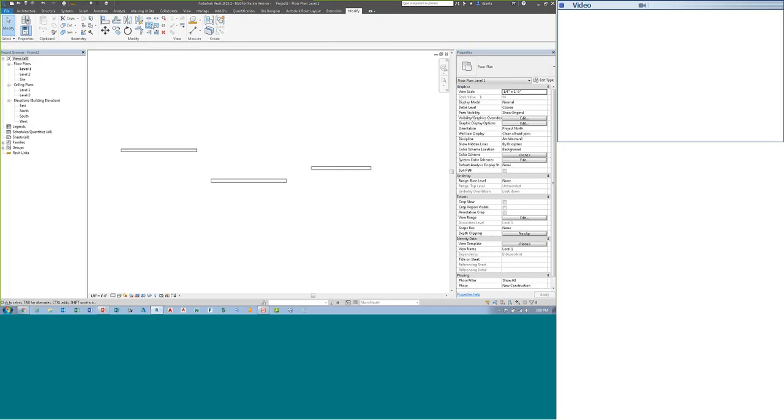Just like all these other commands here, I can start the command, then pick the object, or pick the object, then start the command. So I'm going to use the Align command, pick this to align to, and then if I'm just moving a single entity, I just pick that entity, and it moves up, and I can lock that relationship. Or if I, Control Z, if I start the Align command again, I can use multiple alignment here.